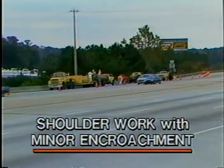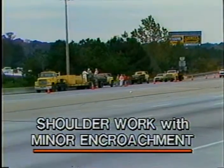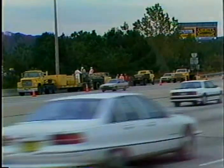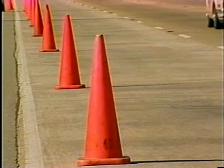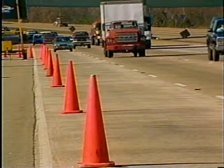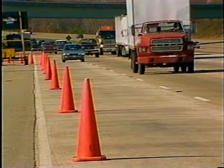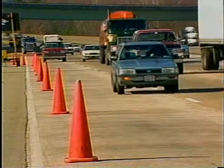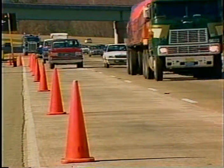When work is on the shoulder or takes up part of a lane, traffic volumes, types of traffic, this could be buses, trucks, and cars, speed and capacity should be analyzed to determine whether the affected lane should be closed. Now, the lane should not be reduced to less than 10 feet. You can consult Part 6 of the Manual on Uniform Traffic Control Devices.